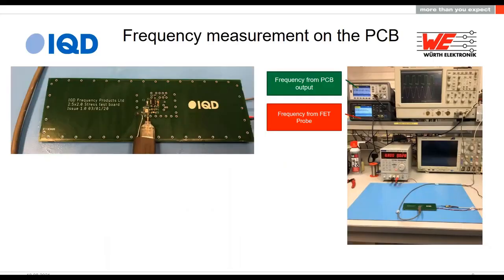Okay, so here we are. We're going to do our first measurement, and there you can see at the top there, we've got our probe. And what I'm doing is I'm pushing the probe onto the active pin of the crystal there. And on the oscilloscope up here, you can see the purple line. That's the frequency coming directly from that probe. So you can see how I'm measuring the frequency. On this instrument, I then take that to a signal output and feed that back into a frequency counter, and I can get the frequency from there. Yeah, pretty easy.